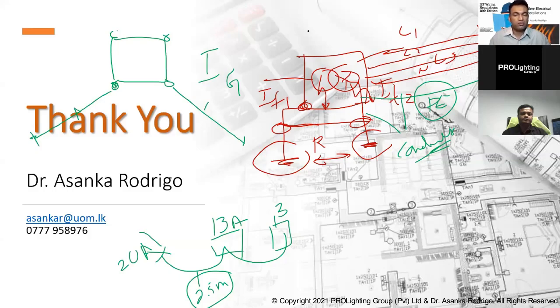If you have an isolation transformer with the SELV system, your secondary side will work as totally separated, where even if you touch a live conductor, you will not get any electric shock. The only thing is, you can put certain types of insulation monitoring devices. Residual current means a certain leakage, and that will be detected by the insulation monitoring devices as well. The insulation monitoring device will give you an alarm if there is a drop in the insulation, so you can act on that, and without disconnecting the system, you can work with that type of system.